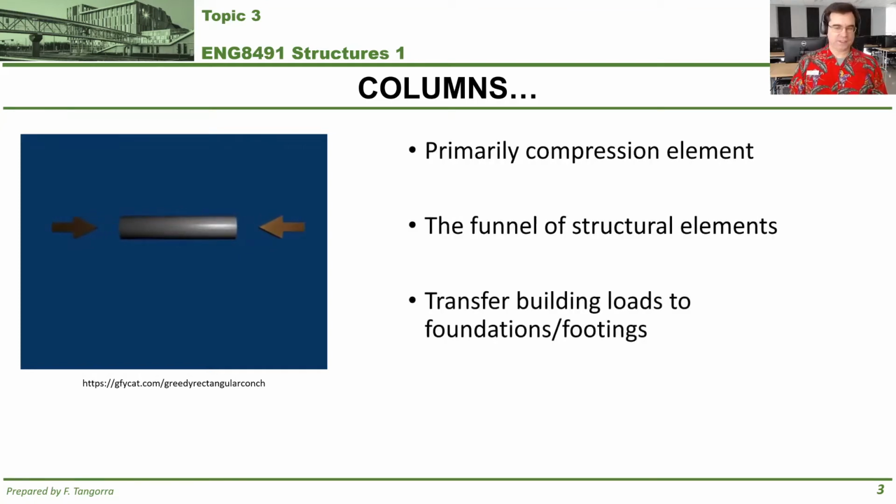For the most part, columns are primarily in compression in structures, and they're primarily vertical, for whatever that definition of vertical is. They're also considered the funnels of structural elements, because not only do they support the floor or roof that's attached to them, they also support the column above.